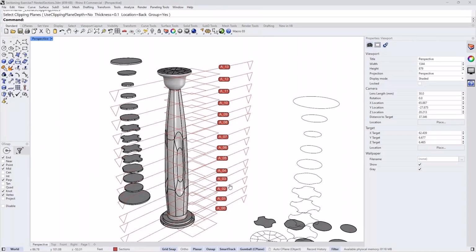That's a good question. I think instead of extracting slices, I would extract sections. This way you already have the curves instead of having to flatten those. I know you'd like to capture the maximum, but the problem with a more dense set of slices is that you have tapers in two directions. Some tapers are smaller going up and some are larger going up. So you need to capture both the top and bottom of each slice and then project onto a 2D plane to figure out your outline for your laser cutter.